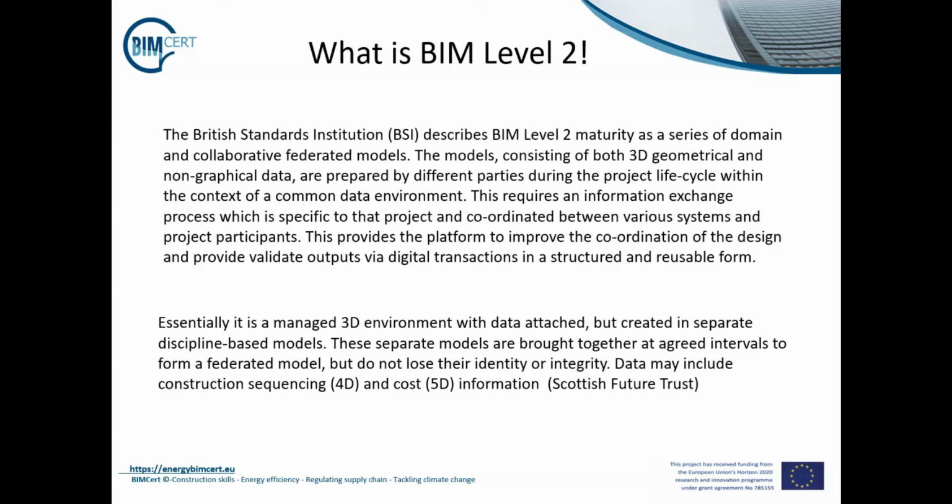This provides a platform to improve the coordination and design, provide outputs via digital transactions in a structured and reusable form. So essentially, it is a managed 3D environment with data attached, but created in separate discipline-based models. These separate models are brought together at agreed intervals to form a federated model, but do not lose their identity or integrity. Data may include construction sequencing and cost information. So simply, Level 2 involves developing building information in a collaborative 3D environment with data attached, but creating separate discipline models.